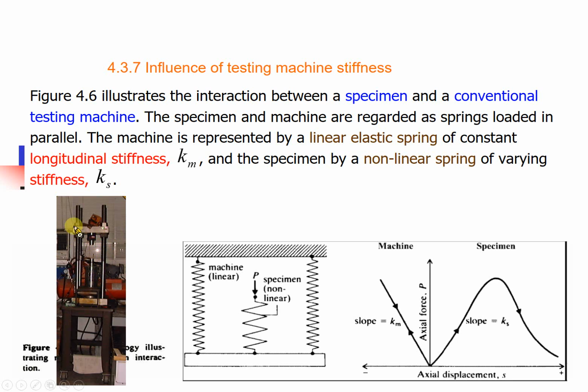If you have a very strong loading frame, then when the rock moves up and touches here, even though you still pump the oil into the hydraulic pumps, the frame will inhibit it from moving upward. Can you understand? There will be the stiffness of the loading frame.